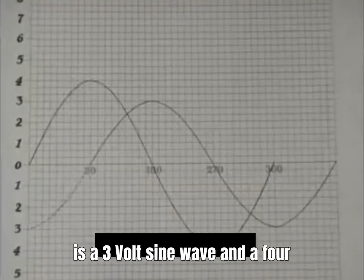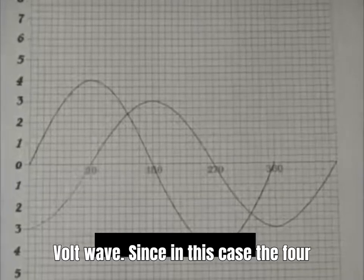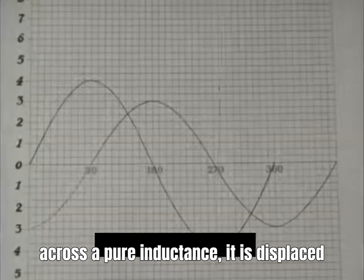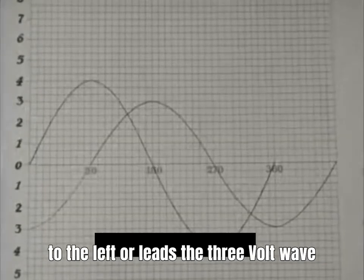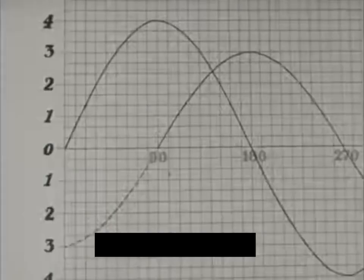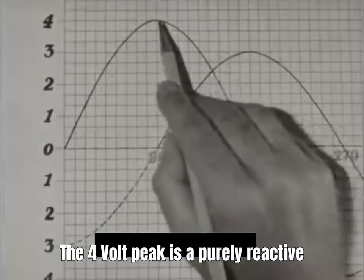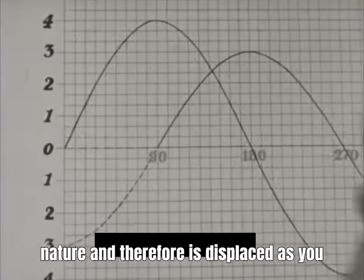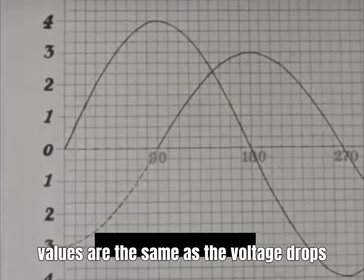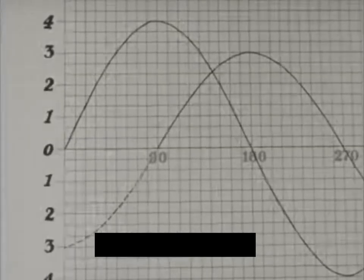Here again is a 3-volt sine wave and a 4-volt wave. Since in this case the 4-volt wave represents a voltage drop across a pure inductance, it is displaced to the left, or leads the 3-volt wave, which is due to resistance alone. Here is a 3-volt peak. The 4-volt peak is of purely reactive nature, and therefore is displaced as you see it.